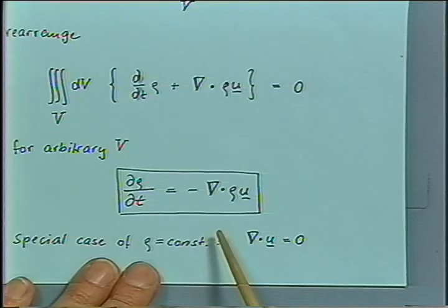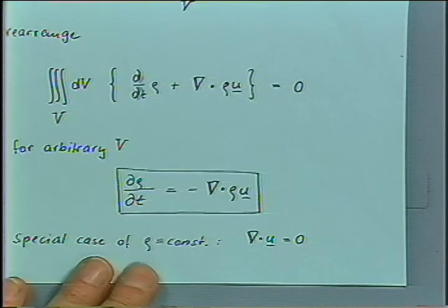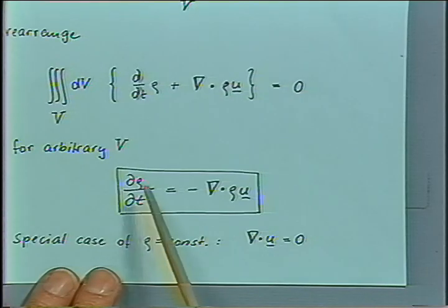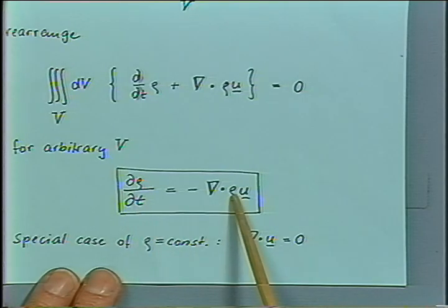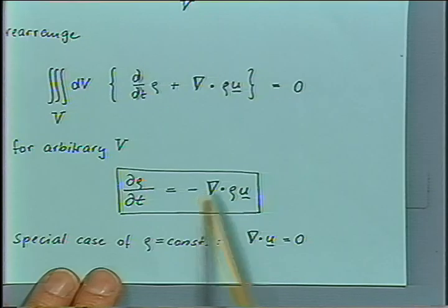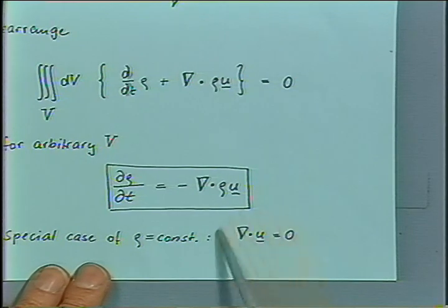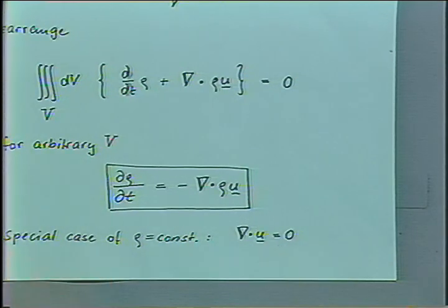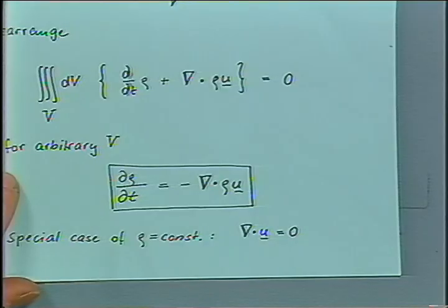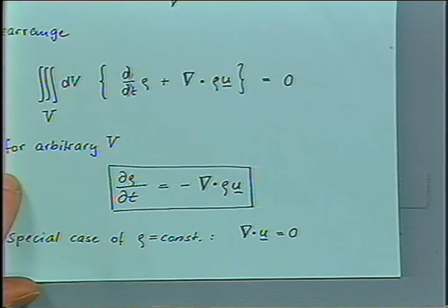If we take a constant density now, if we simplify the problem, we could say, well, the density is constant. This term drops out. Density is constant, goes outside here, and this term is equal to 0. So the expression reduces to the divergence of the velocity equal to 0. And in flows at constant density, we will use this expression for describing constant density. That's the equivalent. Divergence of the velocity equal to 0 in all cases.